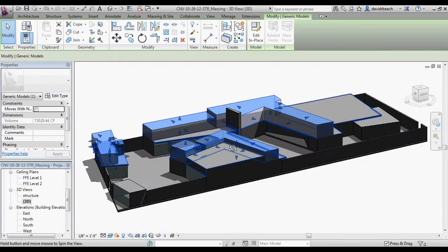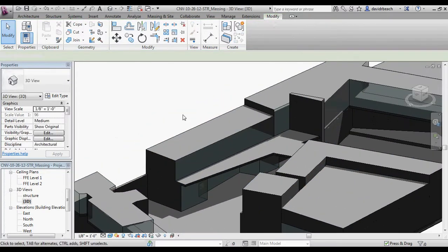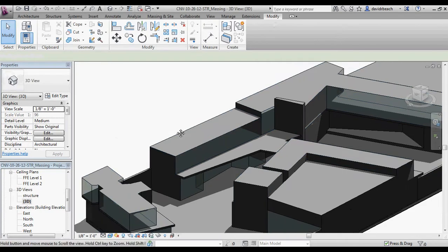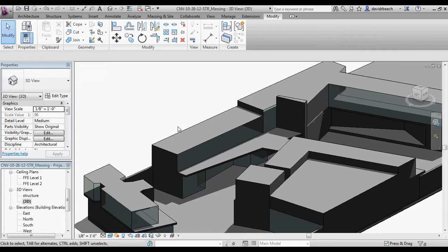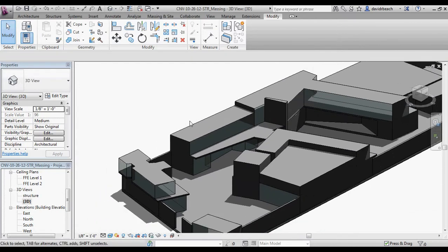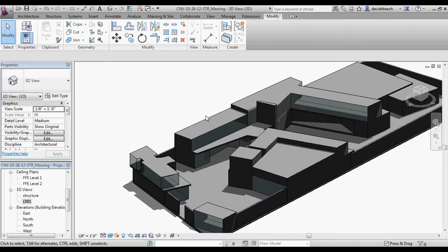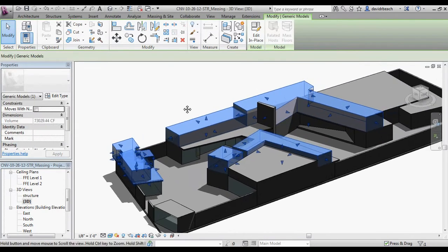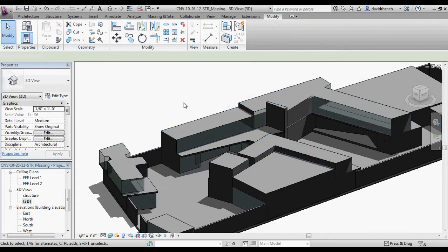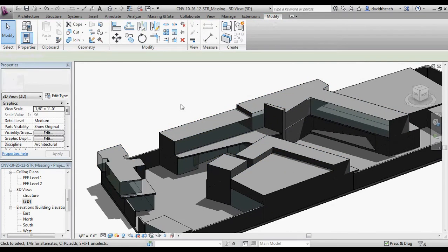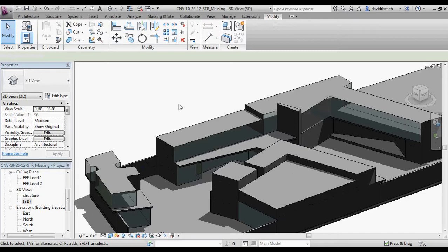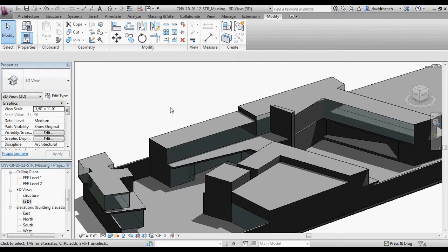I know what my forms are, and I know where I kind of want it to go, but right now I need to start looking at what some of the loads are. So rather than employing a simple rule of thumb, such as a beam's depth is 1 inch per foot of length, so if something is spanning 20 feet, it's 20 inches in depth, which is where I've been at in my structural design career as an architect, which is kind of a scary sentence, I want to start employing some software to get some more realistic numbers earlier on in the process.